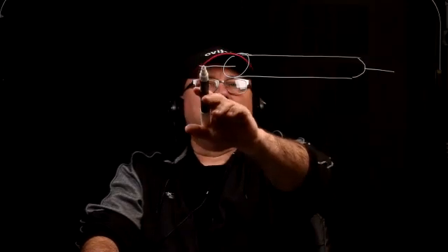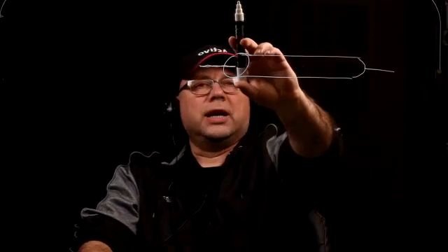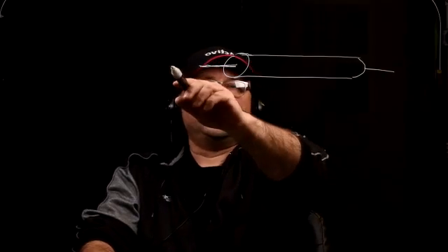The other way of eliminating crosstalk would be, here's another idea. It involves two conductors, and one conductor is the outer shield, and the other conductor is another wire that is inserted into it. So it's a conductor inserted into another conductor. The wire that goes inside provides the signal path. The other conductor that is around it provides the return pathway for the electric current and also acts as a shield. These two conductors, the outer conductor and the inner conductor, share the same axis.